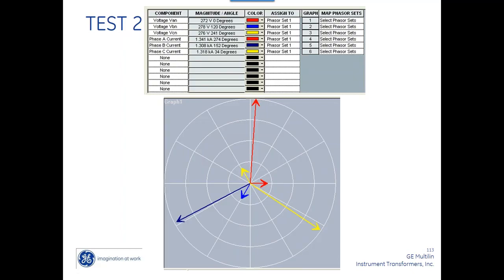Somebody want to answer? How do I fix this? A and C phase are backwards. Swap them. That is correct. That's correct, because you've done it 1,000 times. That was Billy Sanders for those that didn't know it. A and C phase are backwards, so you've got to physically put the wires going to A and C to C and A. A to C.